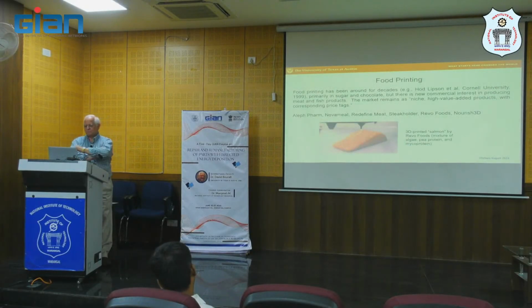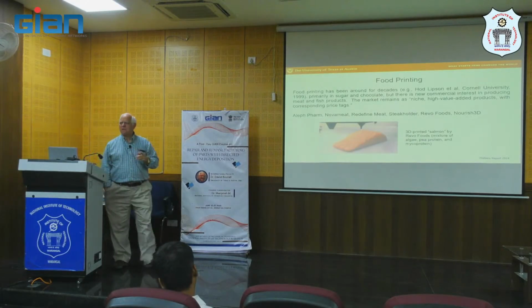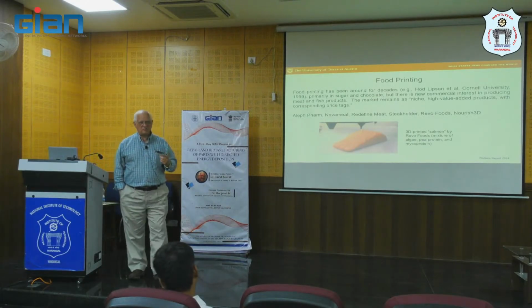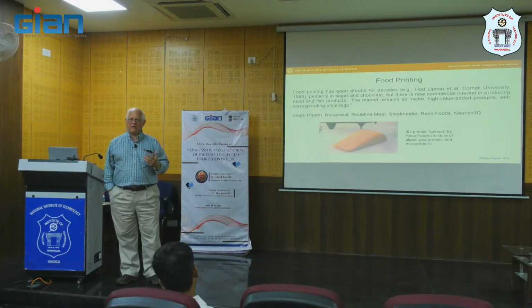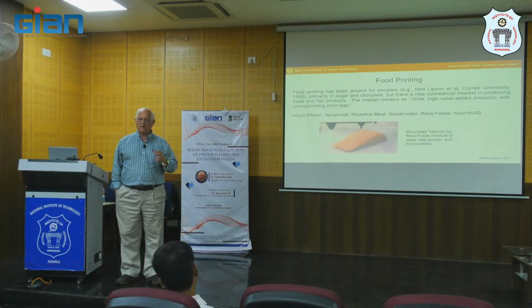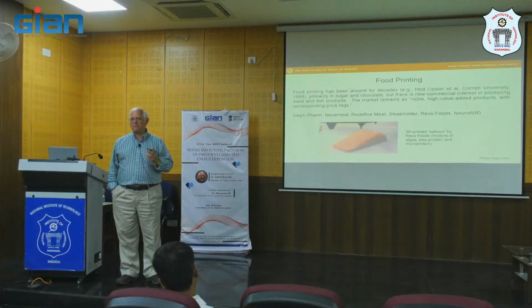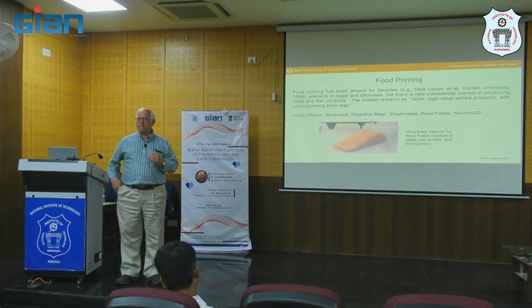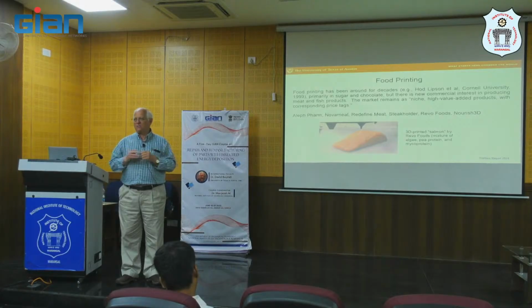Oh, I can't remember if I mentioned it, but with artificial intelligence, the technical advance it can offer is this: most additive manufacturing processes have, if you really counted all of the possible variables, maybe 75 or 100. What we do today is pick out the 3 or 4 most important, like the energy, power, the scan speed, the scan spacing, and the layer thickness, and we work with those.